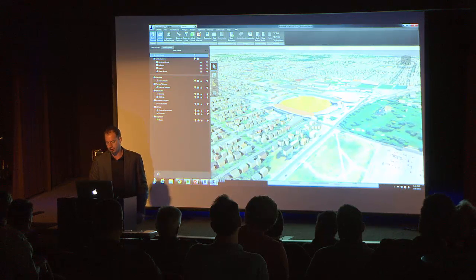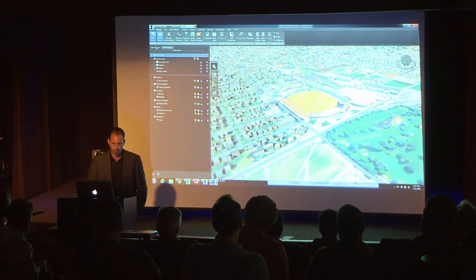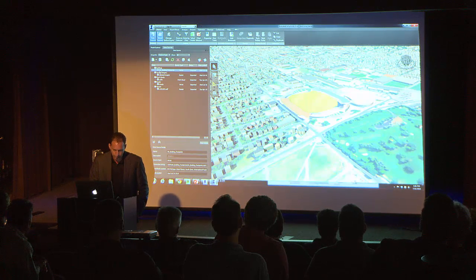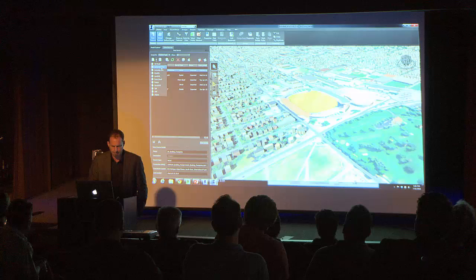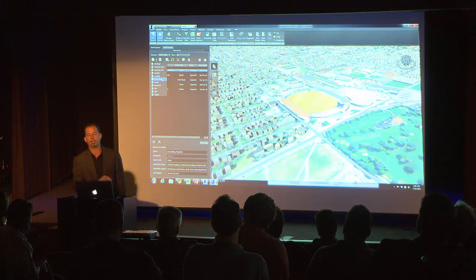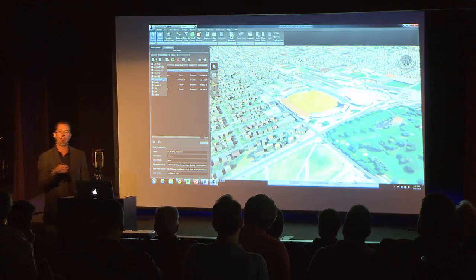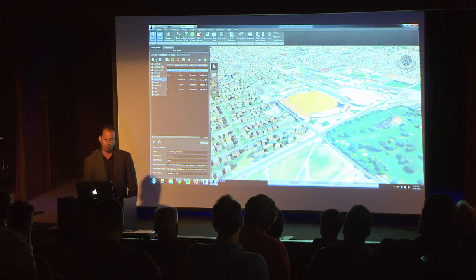Well, I'll just go ahead and leave this in here to kind of speed it up a little bit. But the other thing you do is just go to data sources, just like we've been doing. You'll notice inside that list, you can also add a point cloud. And click on that, go locate the point cloud, drop it in. If it already knows known coordinates, it should go to the right spot. If not, you can actually drag and drop it and put it wherever you want to.